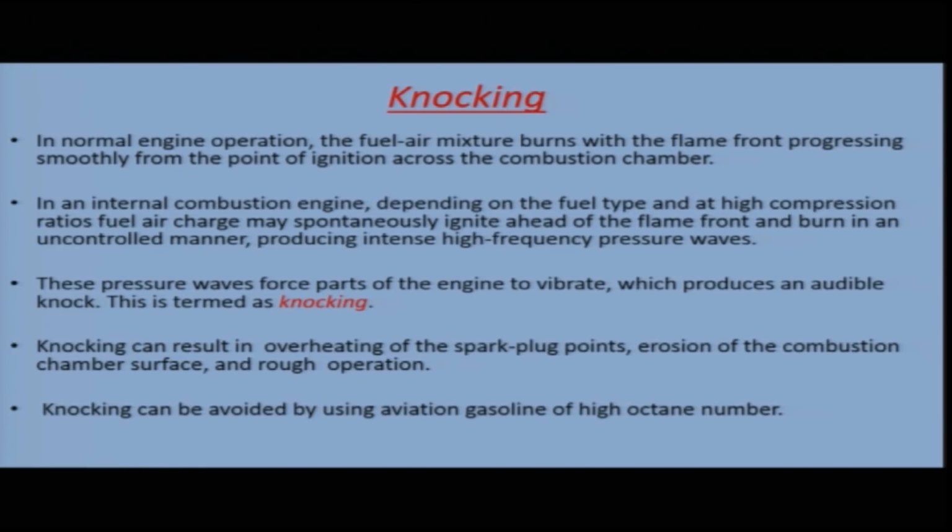But in this case, the ignition may be spontaneous, maybe in an uncontrolled manner, ahead of the flame front, and it will produce intense high frequency pressure waves. These pressure waves will cause the engine to vibrate, which will produce an audible knock. This is termed as knocking.